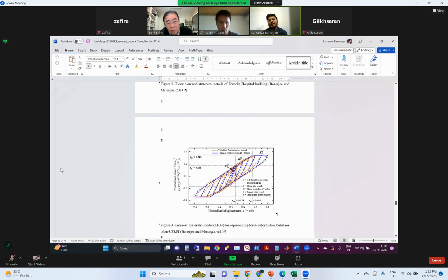I was conducting some preliminary investigations, and what I found is that the second frequency is always good for reducing the base displacement under severe earthquake excitation. However, for slight to moderate wind conditions, the structure does not vibrate enough to go into the second frequency. There, the first frequency is more important, and in the first frequency I don't have a significant amount of damping. You also pointed this out in one of the meetings.